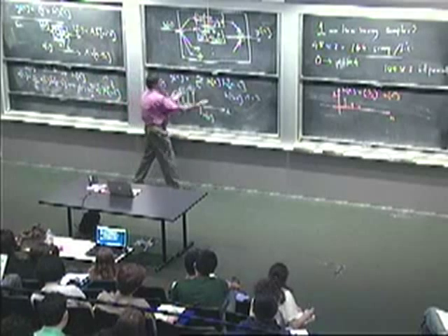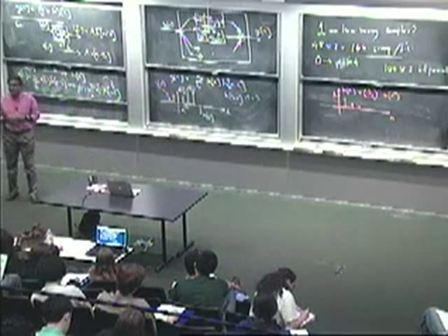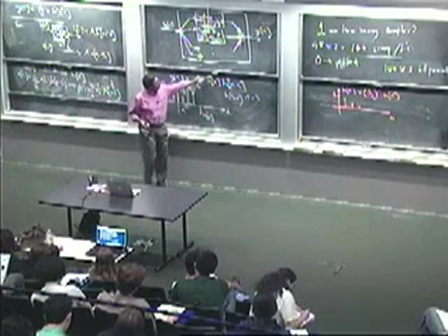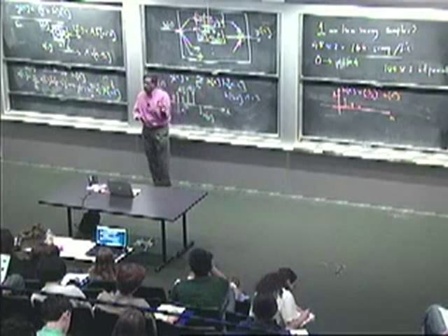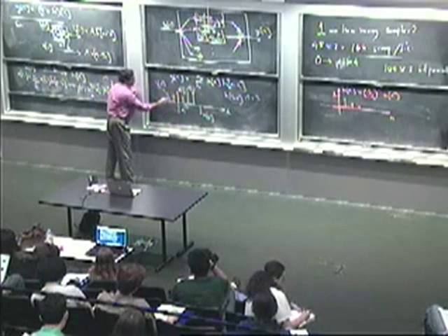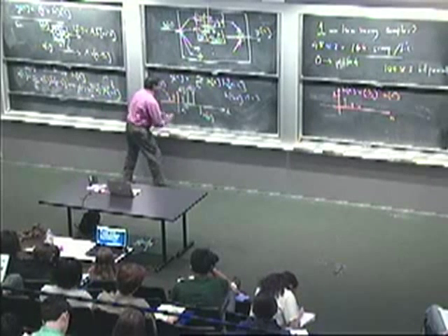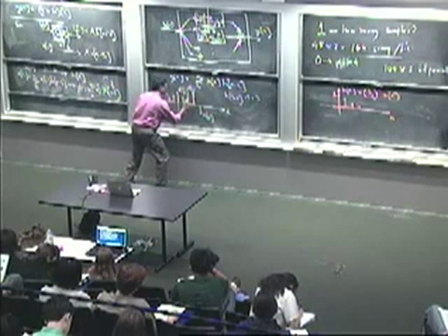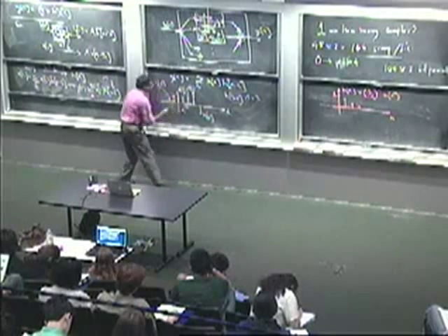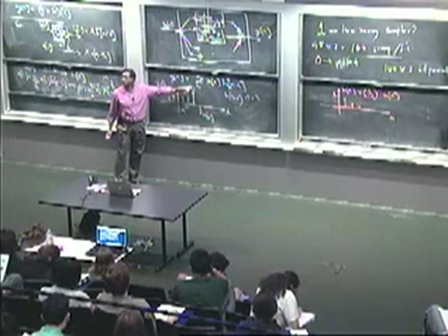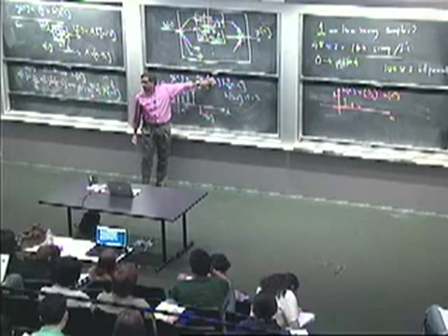So now, on a single figure, you've managed to plot these two. What's the remaining operation? What you've got to do is the point-by-point product of these two waveforms and sum over the entire time axis. It's like taking a dot product, right? So you're going to take this value of the red curve. Well, actually, let me slide it over. Let's do this case. This is the slid over case, right? You're going to take every one of the purple values multiplied by the white and sum over the entire time axis. That's an implementation of this.